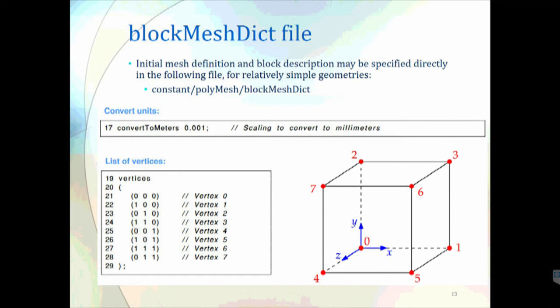Also, at the top of the OpenFOAM file, you can write a convertToMeters statement. The convertToMeters statement will enable you to convert all dimensions to your specified units.